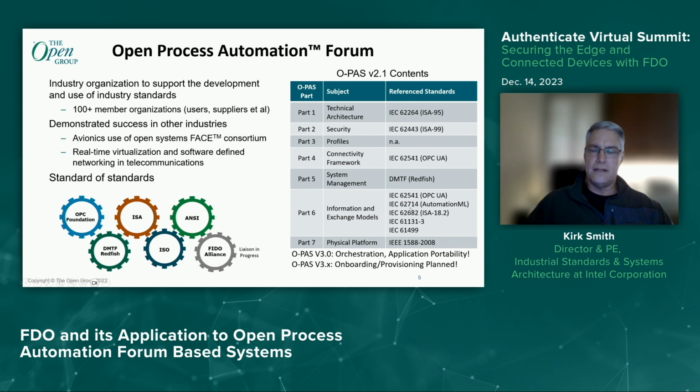And then you've got AutomationML, which is right now targeted for exporting out of the builder tools that most distributed control system vendors have for putting together control applications, usually drag and drop type implementations. But the standard there to export those configurations is through AutomationML. So maybe there's not much to worry about here, but maybe we do need to have hooks for FDO that we reference in those XML-based signatures as part of that configuration that ideally gets imported into a control system to drive its configuration.